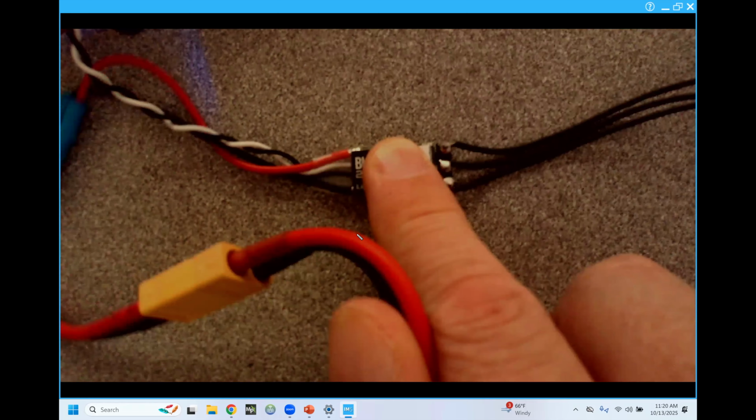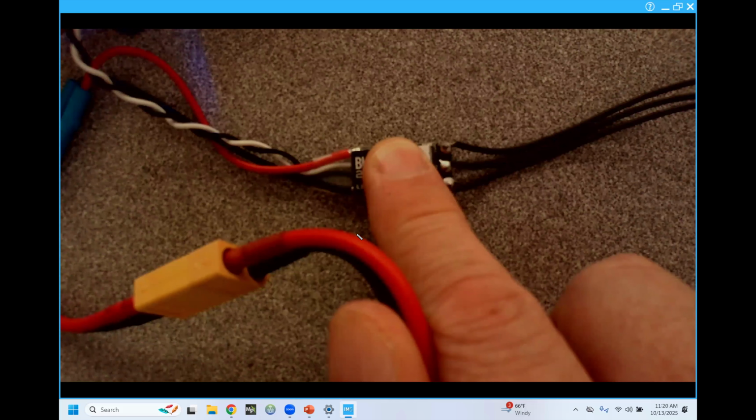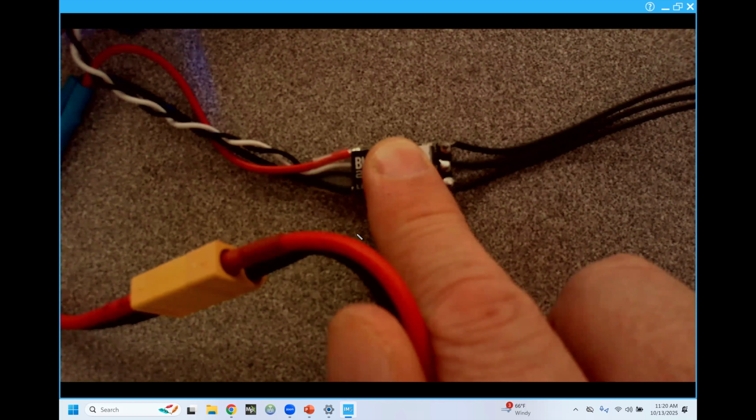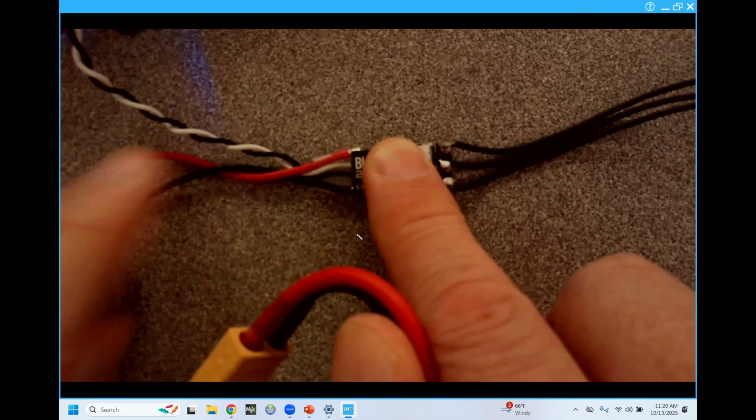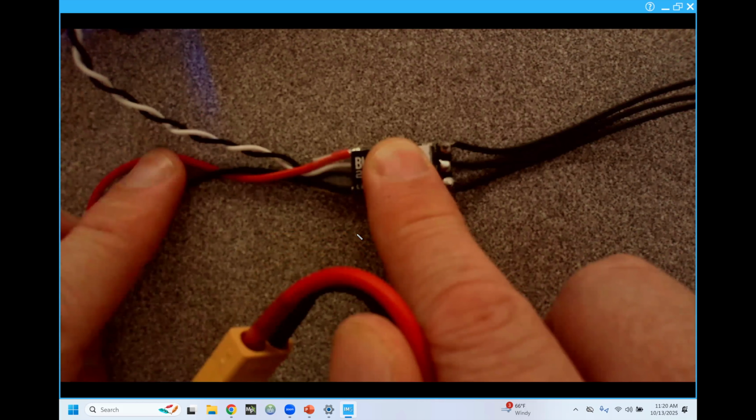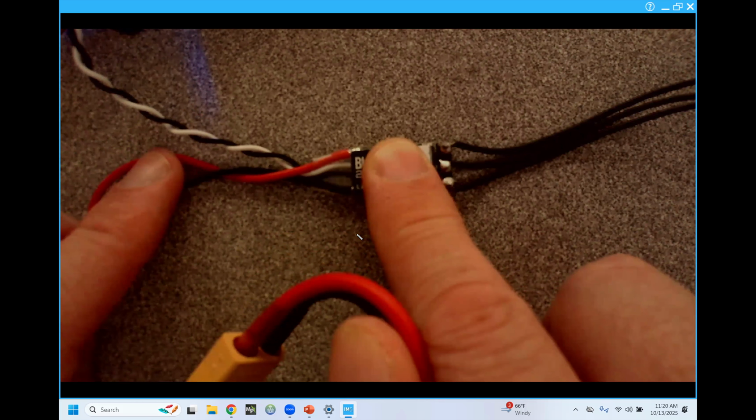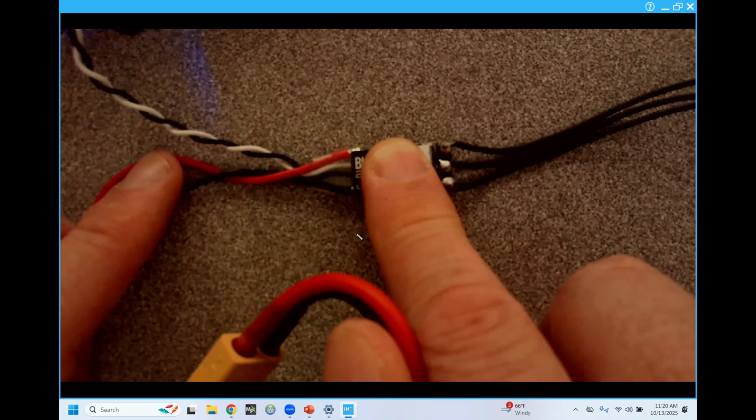So your flight controller has 2 ESCs out. It needs to be split into 4 individual motors. So the red wire that comes out of your flight controller will have to split into 4 red wires to go to the speed controllers. And then once you do that, your drone will be ready to fly. And you can fly it in the drone cage in manual mode if the radio is working, which was the other milestone.